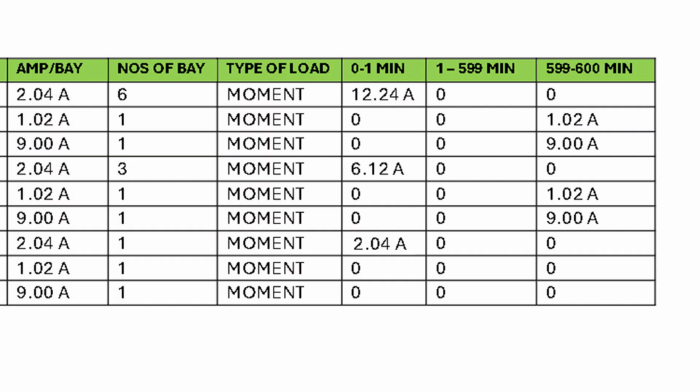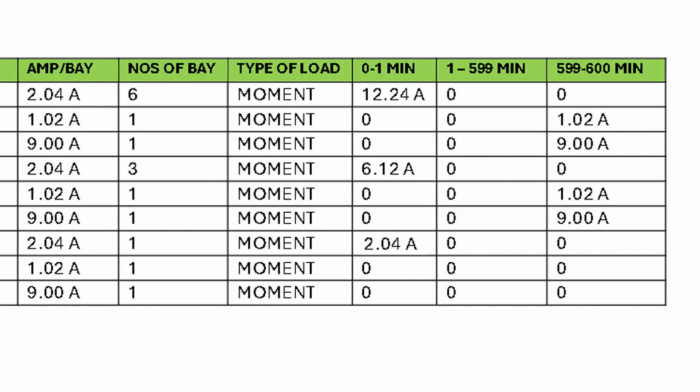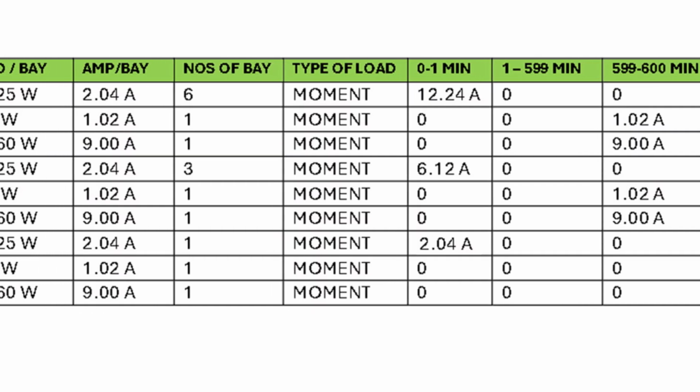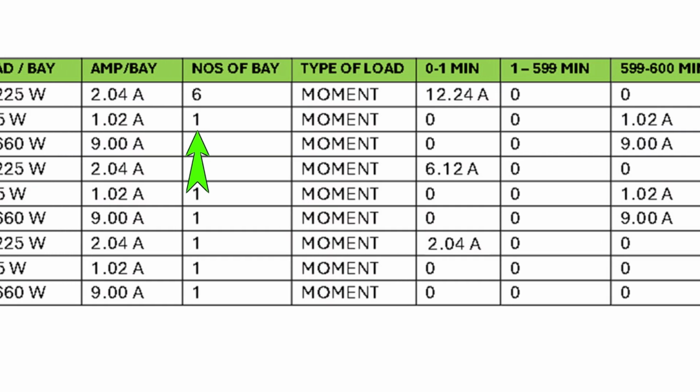We have already discussed that for the re-establishment of AC power at the end of the load cycle, meaning after 10 hours, we need to close at least one circuit breaker. So we will consider closing one circuit breaker of the 220 kilovolt system, one feeder. And associated spring charging is 9 amperes.